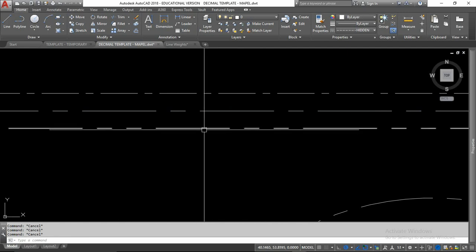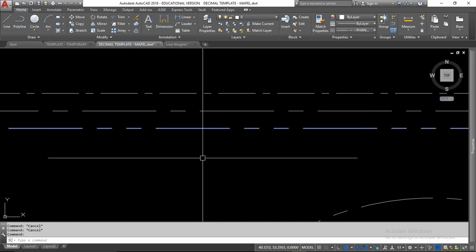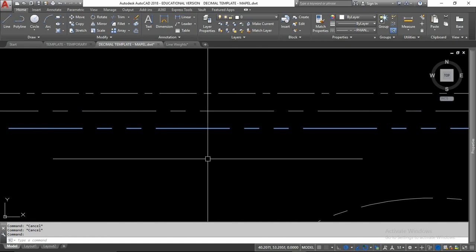Okay? Phantom line's a common one used for section or cutting plane lines to get section views. In surveying, it's a very common one used for properties or boundaries. A few other options, manufacturing, technical drawings, or mechanical drawings. It's common to use to show a second position of an object, such as, I believe that was problem number 13, showing that rotating or adjustable link.